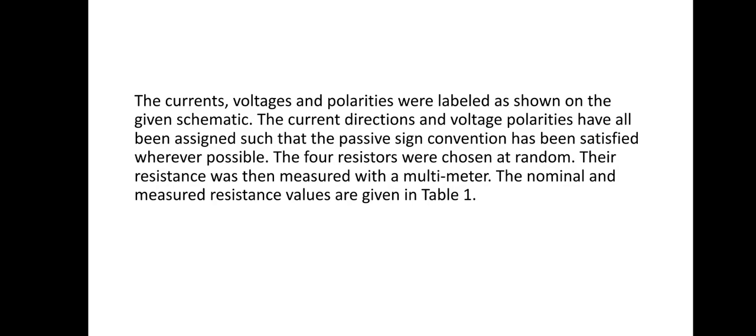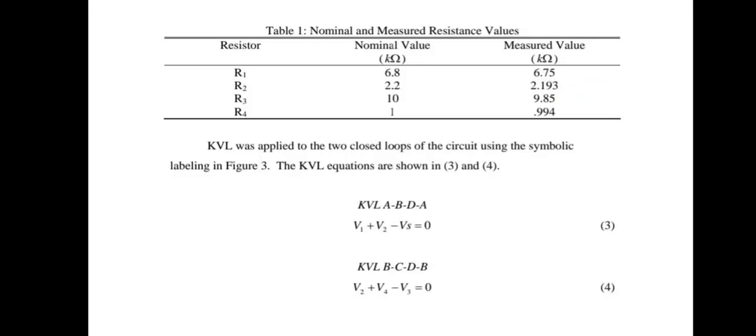The simulation of the circuit verified KCL. PSpice found the sum of the two currents exiting the node to be equal to the current entering the node. The experimental results of the KCL test were also close. There was less than 2% error between the measured and calculated I1s. This error is acceptable in stating that KCL is true.